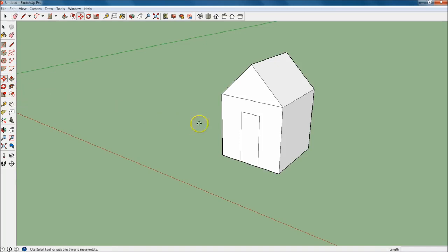That's your move tool. And then what we're going to do is we're going to come over here, and we're going to hover over this line right here, and we're going to drag this down, make sure it's on the blue plane, the Z plane, and then we're going to drop it. And after we've already let go of it, that's when we're going to type in the 6 inches. Now, again, we can do 0.5, or we can just type in 6 and hit enter. Okay, so let's go ahead and check that with the tape measure. Again, you don't need to, but it's always good practice. So come up, 7.6. Great. Hit escape to get out of that because you don't want to put that down.